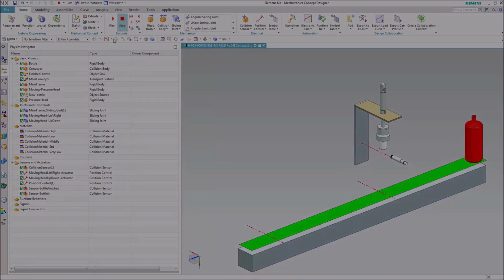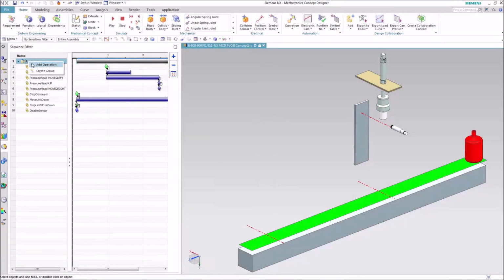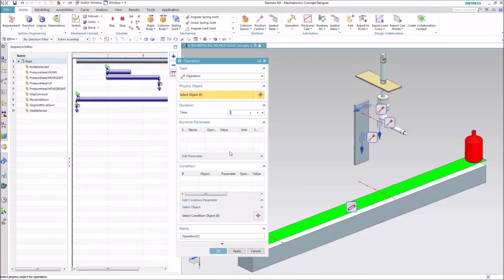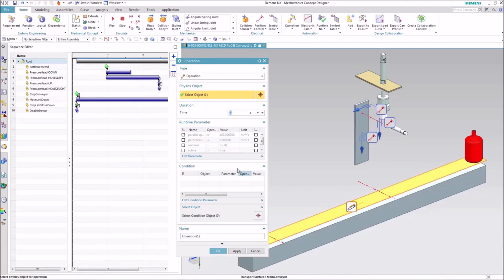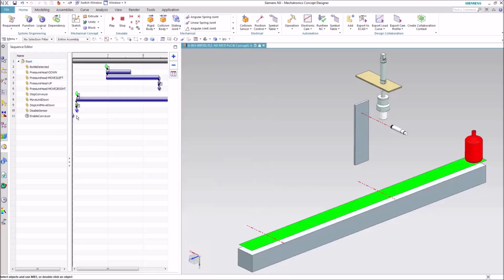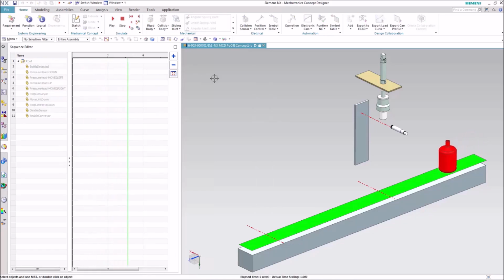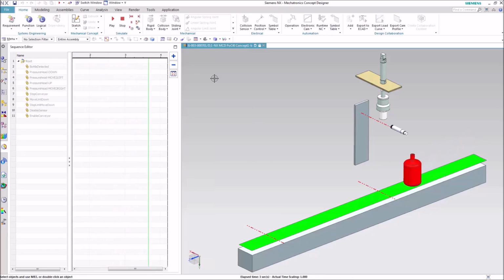But due to a new customer request, the machine must also be able to work with varying bottle heights. At the heart of every industrial machine is operational logic, and we can include this in the first simulation concept, not only the mechanics. This is what will also later become the automation. We now have changed the logic of this concept, so when the first shorter bottle is entering the machine, the height is determined and used for the entire batch.